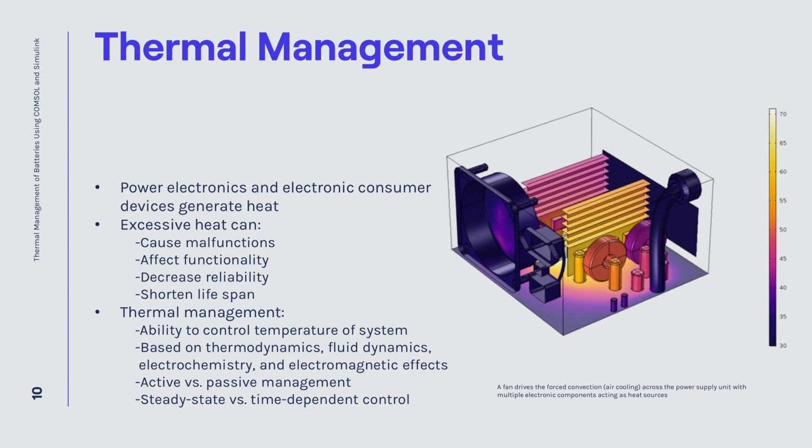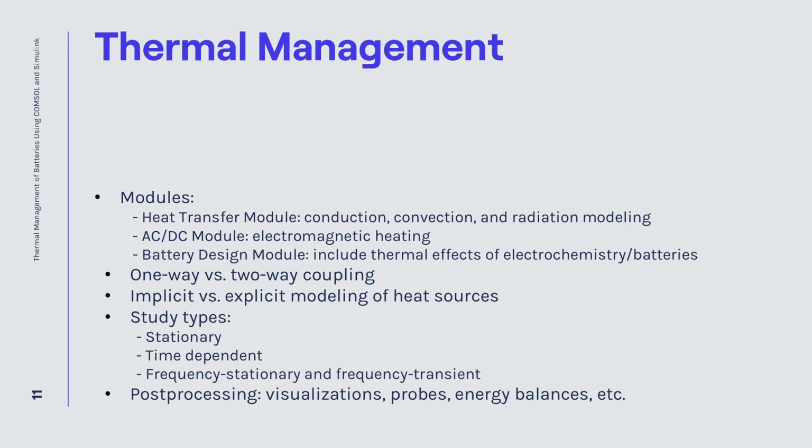So you can have solutions for all of these. You can investigate whether a passive radiator is enough for your design, or maybe you need some active cooling in your equipment. That's also possible. You can search for the steady state solution, or for the time-dependent simulation as well. The Heat Transfer Module has the features I mentioned earlier: conduction, convection, radiation. If you want to couple to other physics like electromagnetic Joule heating, you may need additional modules here.